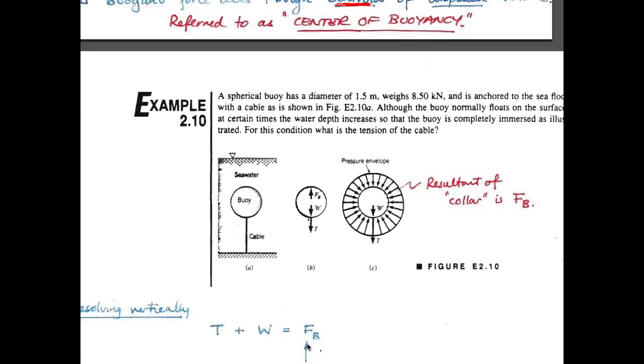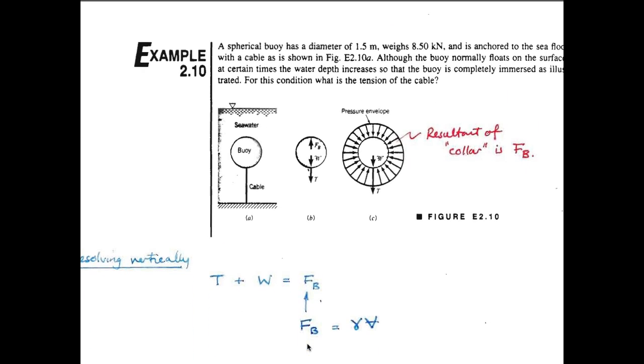Well, you can apply it as a free body just in exactly the same way as we've done in the past. And the idea here is that if you have a buoy that is anchored into the seabed or the bed of a lake, then we can look at the tension that you have to apply in this cable to be able to counteract the buoyant force of the displaced water and balanced by the weight of the metal structure that you have with the air inside it in this particular case, which actually wouldn't register.